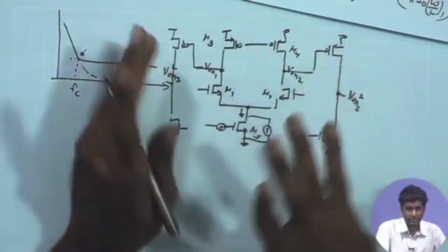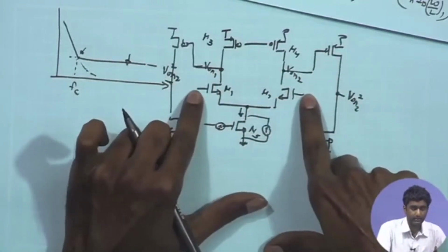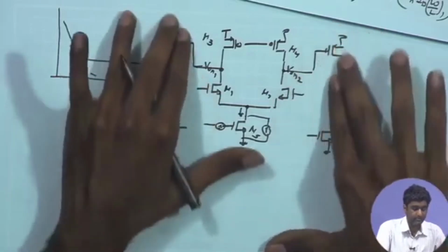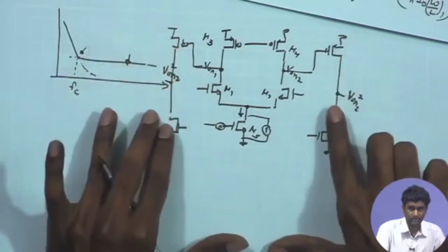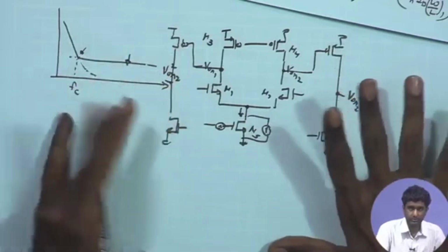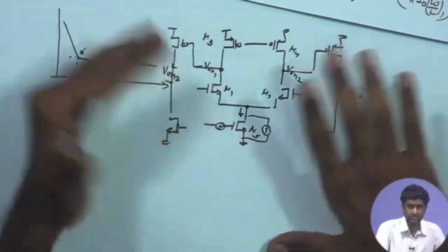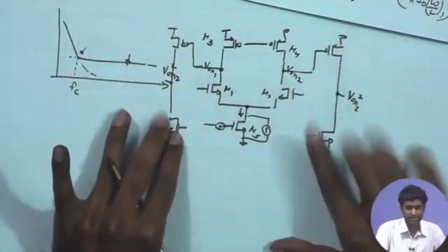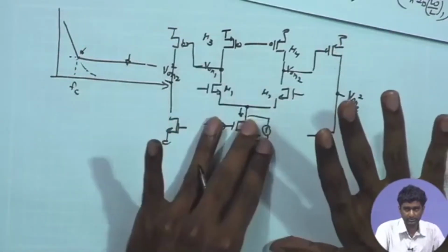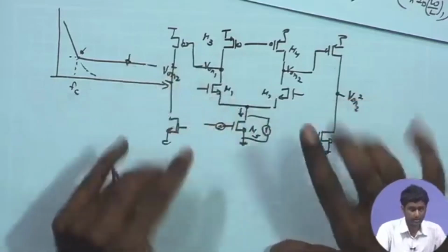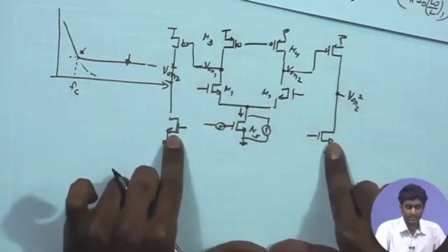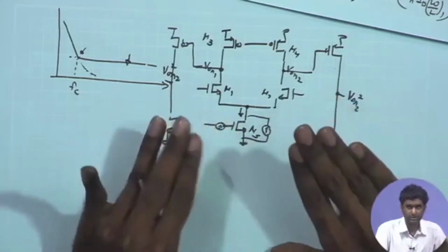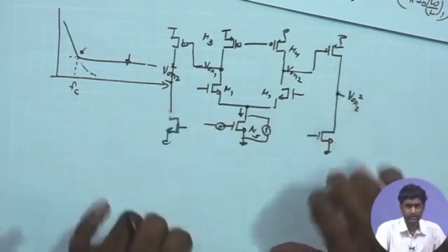stage. So, we are concerned with minimizing the noise contributed by the first stage, and we should just make sure that under no condition the second stage noise is degrading too much. That will not happen generally because of other design constraints. We have the W/L and the bias current in the second stage comparable to the first stage. So, we can try to save some power dissipation by allowing lower bias current in the second stage because it is not so noise critical.